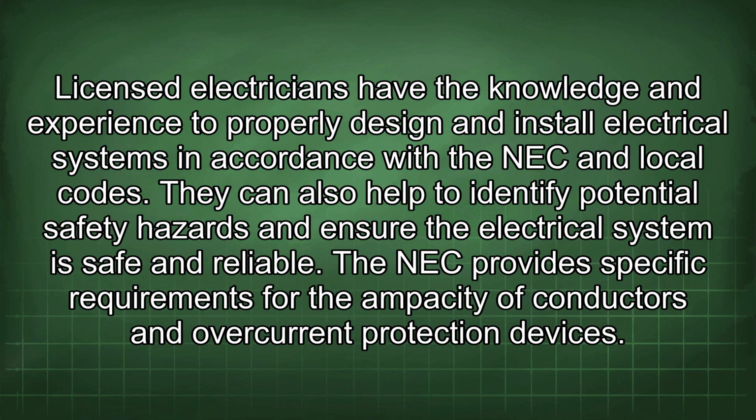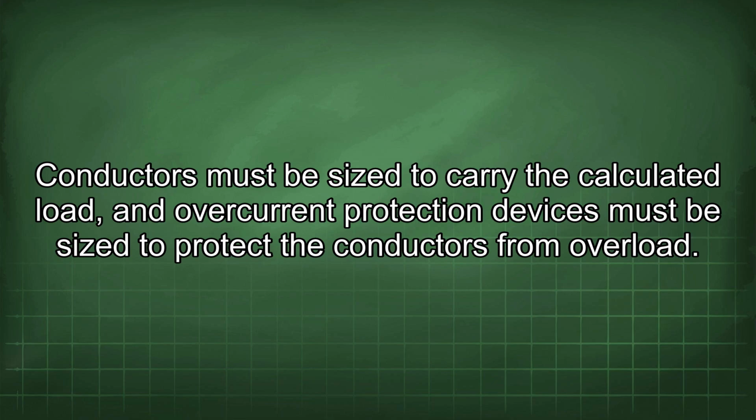The NEC provides specific requirements for the ampacity of conductors and overcurrent protection devices. Conductors must be sized to carry the calculated load, and overcurrent protection devices must be sized to protect the conductors from overload.